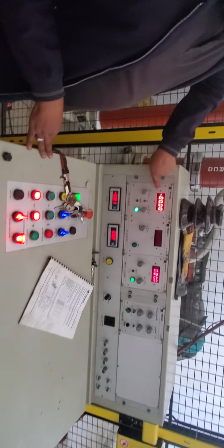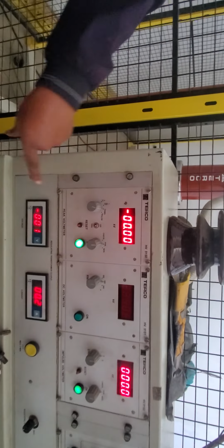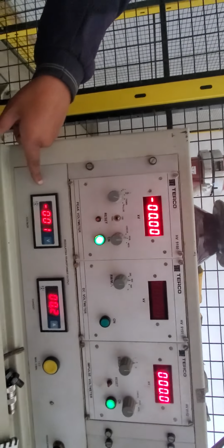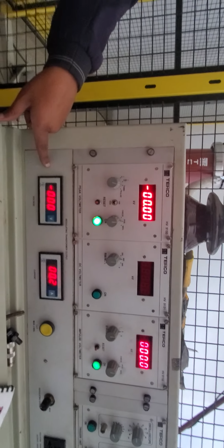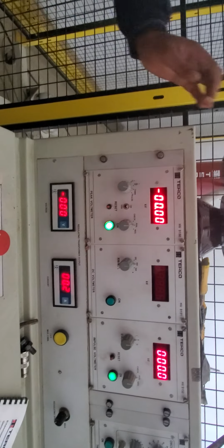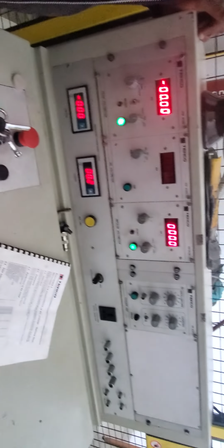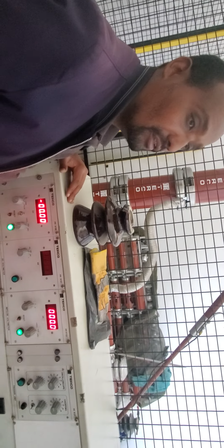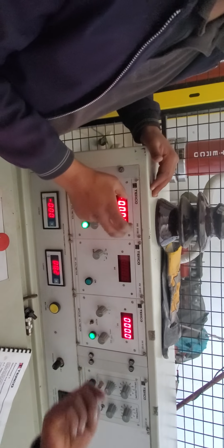So this is the output of the secondary transformer. This is the output of the auto transformer secondary. This is 0. Why? Because the tap changer is at point C, touch line. So the output voltage is 0. So there is no input voltage for the primary of the transformer, so the output voltage from the secondary is 0 volt. Yeah, in the absence of input voltage, there is no output. This is the output of the secondary transformer, or it is the output from the capacitor.